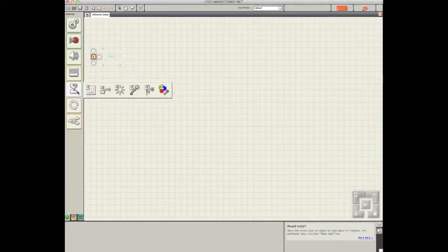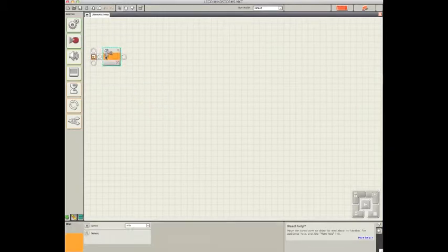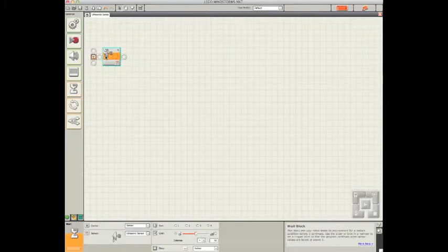The ultrasonic sensor senses distance, so you want the one with distance on it, and that's this one. So what do you think this over here means? Basically, it means that the robot will sense an object that is less than 50 inches away. If I give you an example, let's say you want the robot to go forward until it senses something that's 12 inches away, and then you want it to stop.